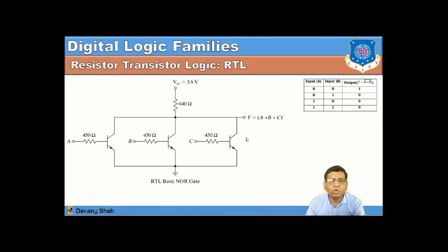This is one more case where we have taken all those transistors in parallel with each other to realize the NOR gate, right? Its logic is simply a kind of inverter logic, but since you are putting all these switching components in parallel, you can realize a NOR gate. Here we have taken the truth table of two inputs, but you take all three inputs as 0 0 0. Here you can see three transistors are connected in parallel with each other.